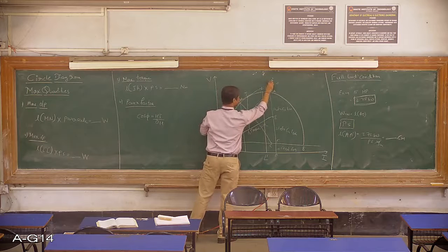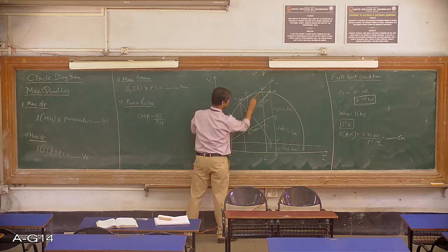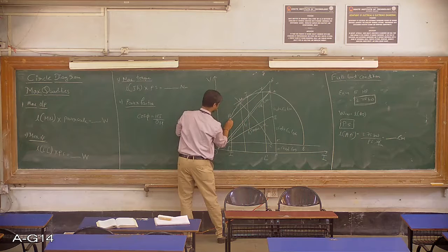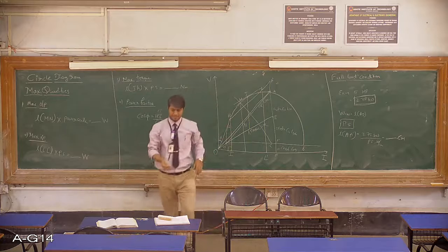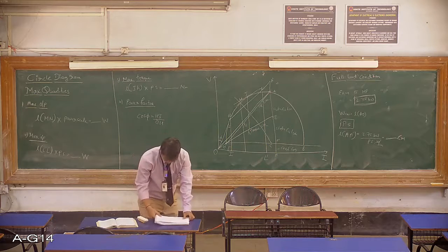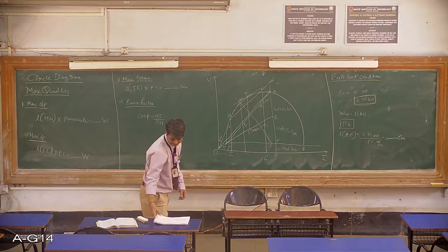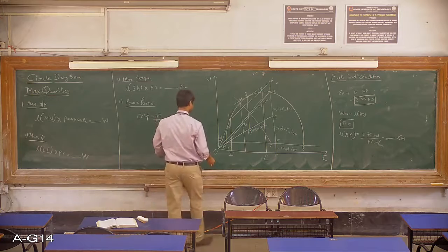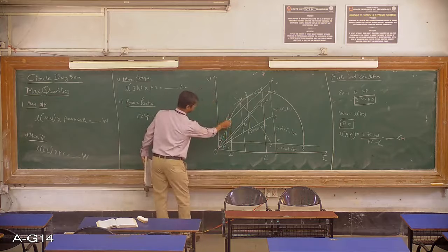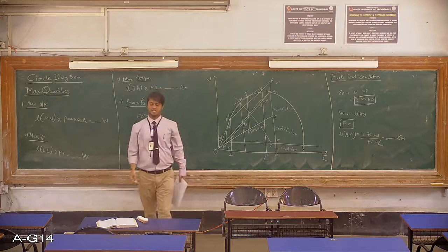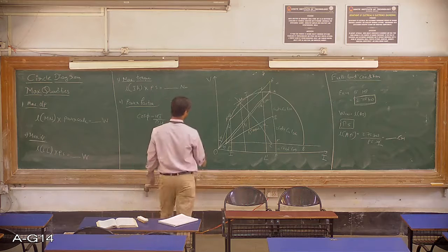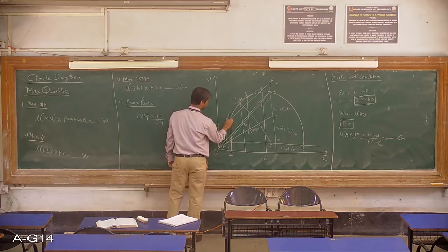So this is the length. Here I am going to draw a line parallel to this output line, and here it is meeting. Okay, and the meeting point, I am naming it as point P dash. Here I'll mark this. This P dash, the point P dash, is the full load condition point. Okay, under full load condition, this is the operating point of the induction motor.